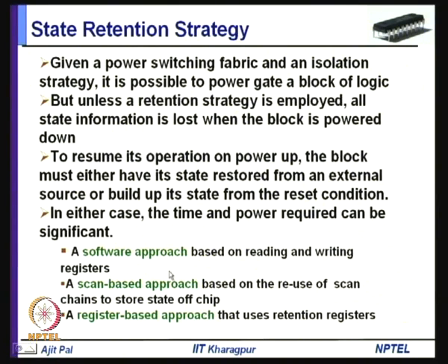In either case the time and power required can be significant, and there are 3 basic approaches. First one is known as a software based approach, reading and writing registers. Second is the scan based approach, based on reuse of scan chains to store the state of the chip, and third is the register based approach that uses retention registers. Let me very quickly go through these 3 techniques.